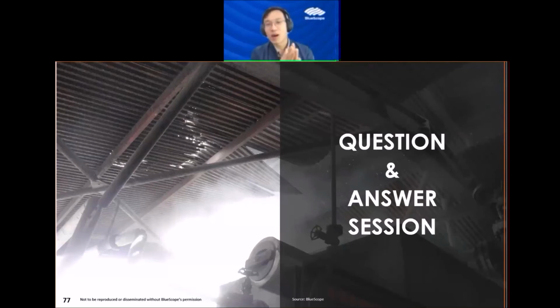The reason why I say this is because relative humidity looks at how much moisture is in your air. If your processes involve steam, steam is basically introducing more moisture into the air. So if you want to reduce the RH for an industry that involves steam, like a palm oil mill, then you need to eliminate the introduction of steam internally.